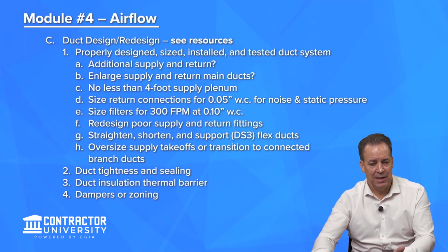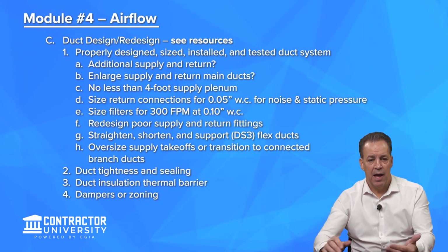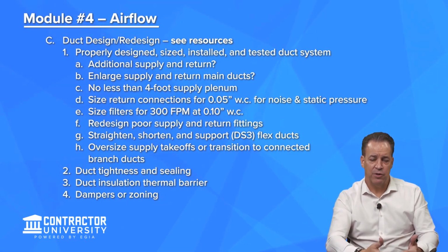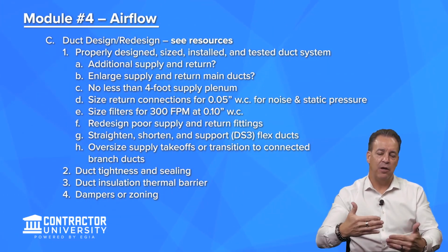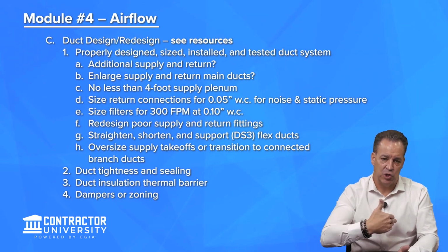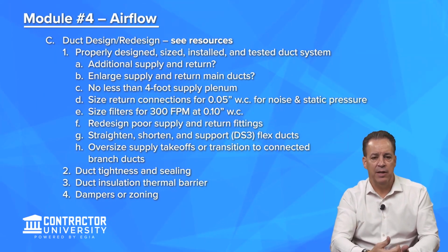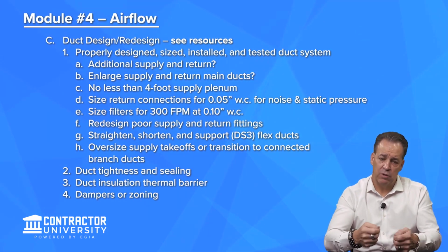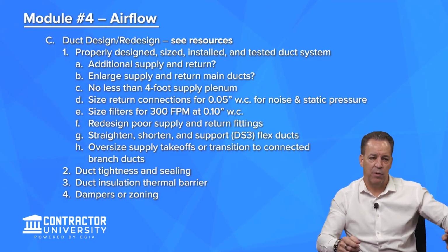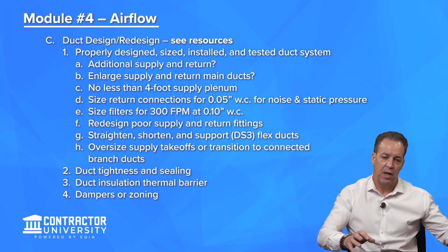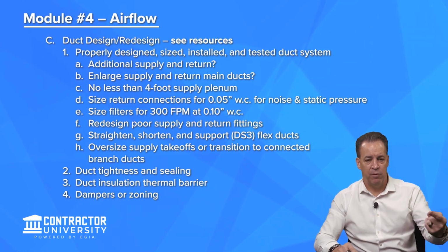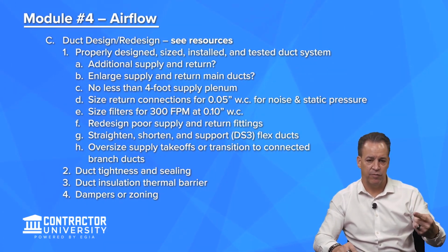Dampers and zoning, that's something to take into consideration as well. The dampers, okay, there's the doors, I call them airflow regulators. They're inside the ductwork. Again, they allow you to shut off the airflow at the source. Registers can be closed, they were just never designed or intended to be closed. And so if customers are closing off registers saying, well, we're not using that room, our kid's off at college and we're empty nesters and we want to direct more airflow. Well, their thought is right, but the intention is right, but the execution is flawed.